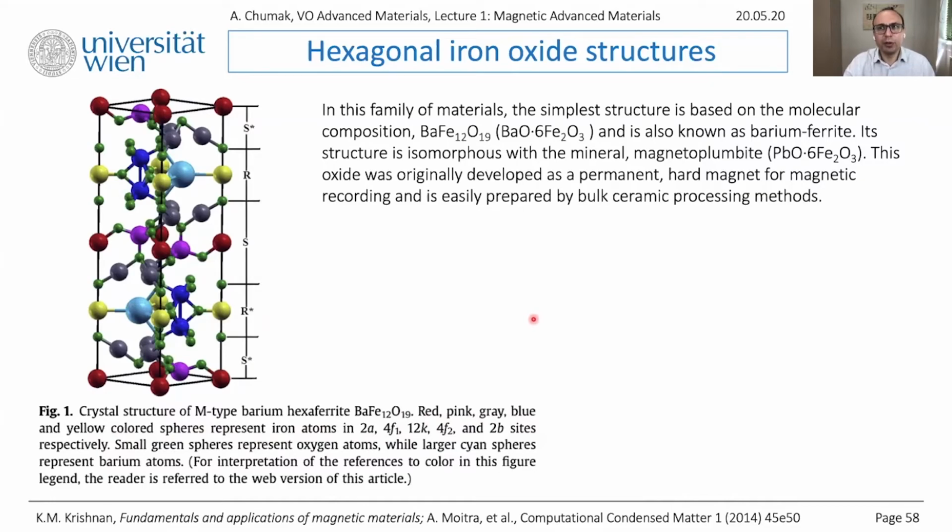crystallographic anisotropy. So we do not discuss crystallographic anisotropy, magnetic anisotropy in this lecture, but it exists. So there is an easy and hard axis of a magnetic material. Sometimes you take a piece of magnetic material and it wants to be oriented along one direction. And if it's a sphere, for example, it's not clear why it doesn't want to point elsewhere. The reason is crystallography. From all possible crystallographic axes, magnetization chooses the direction where total energy will be minimal. And this is named easy axis.